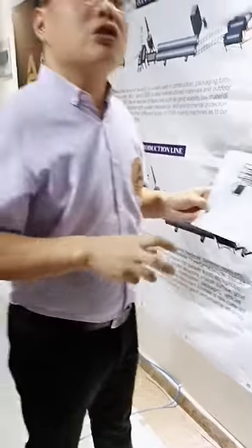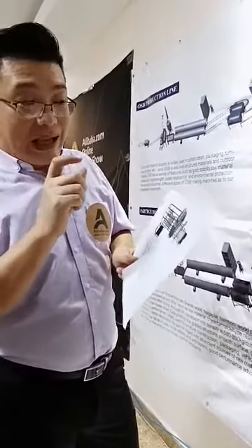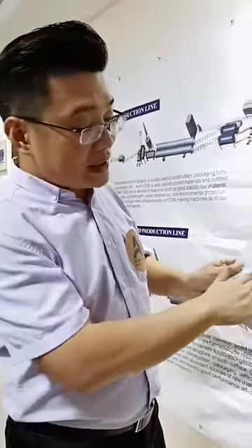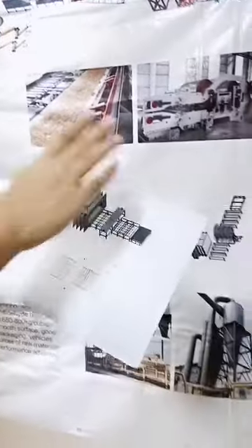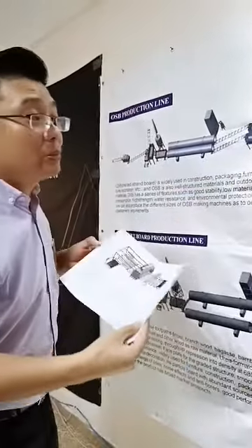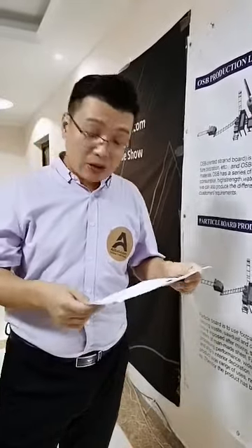side. Actually, for the short cycle lamination, we always have just a single layer, one piece of particle board at a time. But this lamination is very quick. It's always laminating both sides. It just needs about 10 to 12 seconds to finish one press and one lamination. Then it comes out, cut off, trimming, and stacking. Then after lamination, this is the end of the particleboard process. So then it can be used for furniture and for some other purposes.